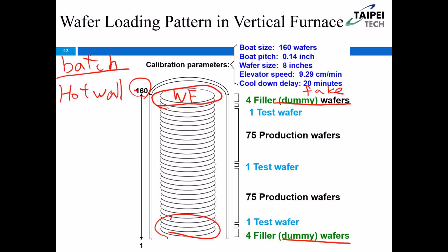But you will wonder, so can I just remove the dummy wafer? No, you cannot do that. You cannot remove the dummy wafer. Today, if you remove this 4 dummy wafer, then this wafer will become the dummy wafer, okay? This wafer will become at the edge of the quartz tube. So this wafer will become the worst quality, the worst outside quality here, okay?